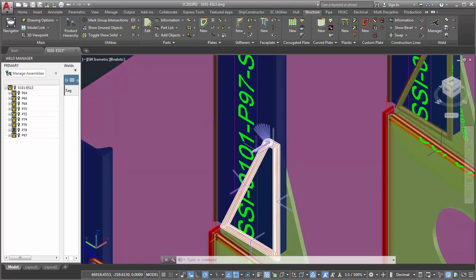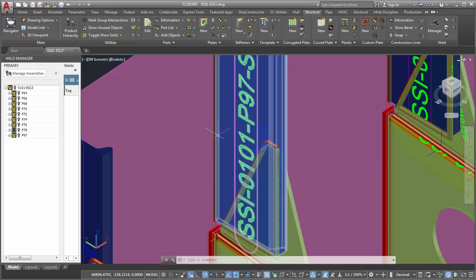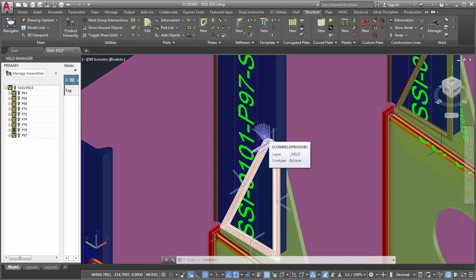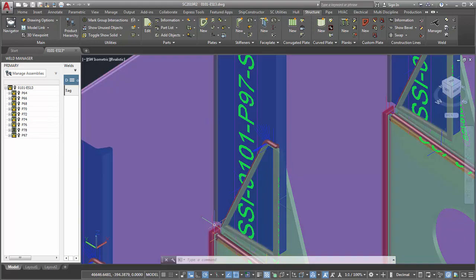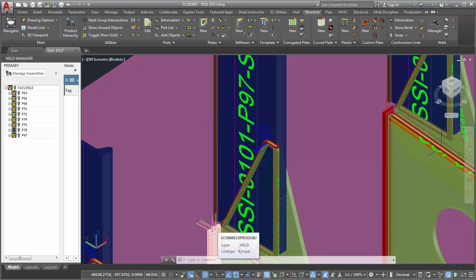So we're going to use the terminology normals. And what is normals? Well, essentially, it's a normal vector that comes out of the face of a surface of two welded parts, perpendicular to the surface face. This is what we refer to as normals. As you can see, some normals show as blue, which are good. They were calculated fine, successfully generated. The ones that show in red were the ones that we could not successfully calculate. So they're defined as red in here.